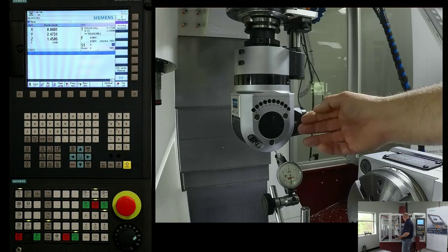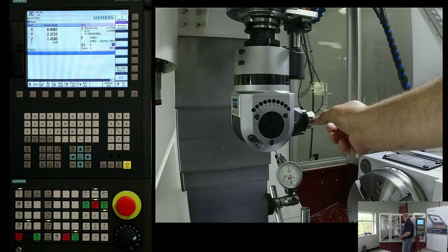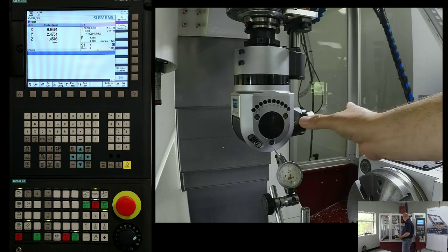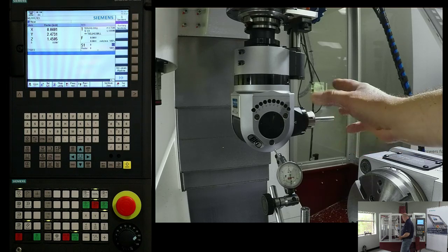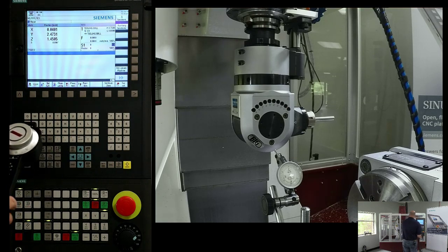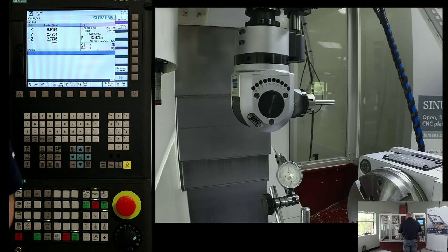So if I have a stop here and I know I want to be able to repeat tooling and I want my offset to be the projection out, then I can do this step. If not, I can actually leave this step alone and let this total distance be handled in the tool offset. I'm going to show you how to do it the other way. Now, before I take that measurement, what I am going to do is I'm going to change out my tool.